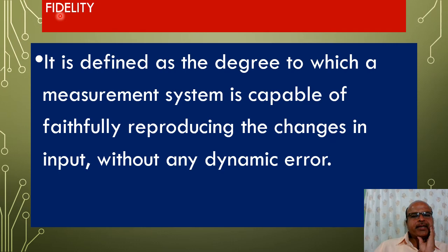Then the next term is fidelity. It is defined as the degree to which a measurement system is capable of faithfully reproducing the changes in input without any dynamic error. If you observe the technical specification of any mechatronics equipment or electronics equipment, all these measurement parameters are specified by the company, meaning all important parameters, and fidelity is also mentioned. So it is defined as the degree to which a measurement system is capable of faithfully reproducing the changes in input without any dynamic error.